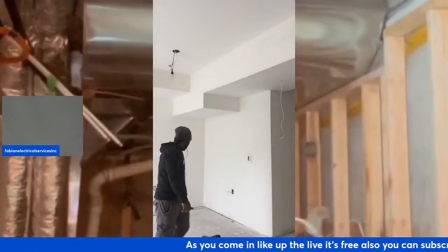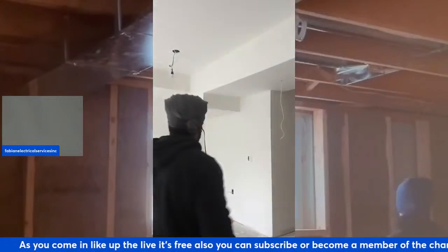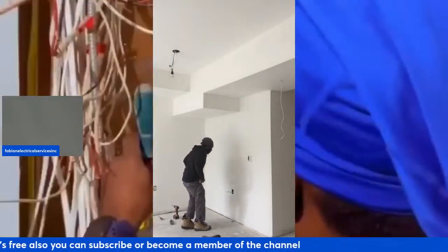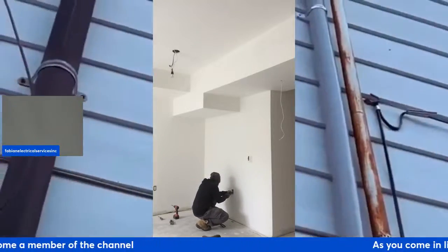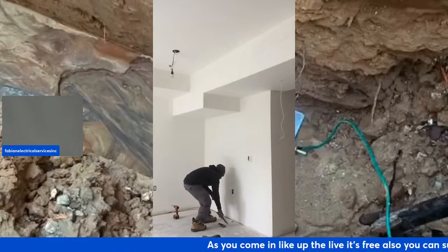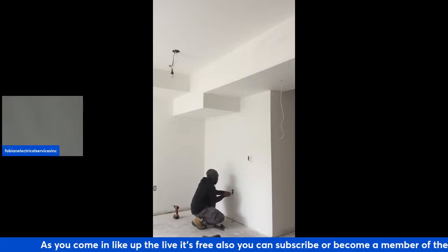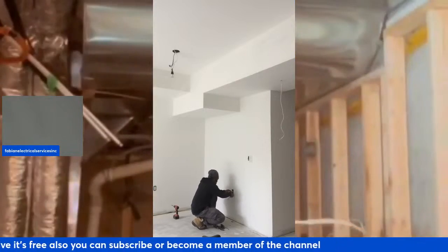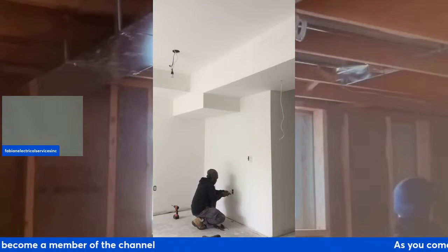Again, this room here is basically regular receptacles that are being installed. 15 amp tamper-resistant receptacles, which are going to carry the AFCI protection, the arc fault protection. Why is it carrying that? Because the OESC 2024 states that receptacles, 15 amps, 20 amps, I believe, will carry an arc fault breaker.